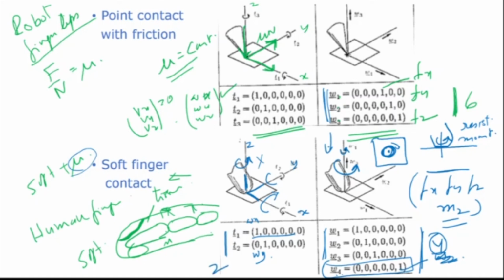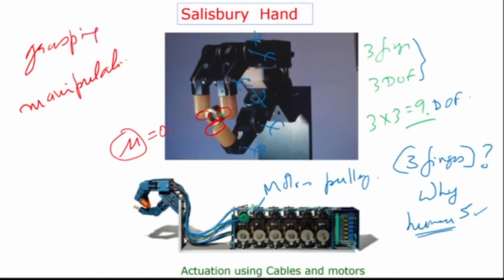Before we analyze any multi-finger manipulation, let me make a point here. If you are wondering what the relation is with motion planning or path planning, in this particular application I want to impart a particular motion to this nut. For example, I want to tighten this nut, so I have to rotate it about an axis. To rotate this nut about an axis, I have to impart forces and moments. And rotation means I have to impart some desired velocity.